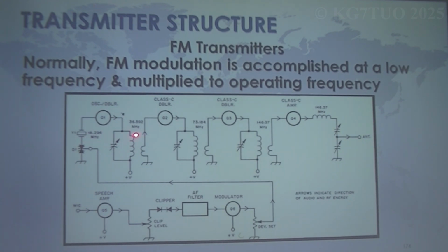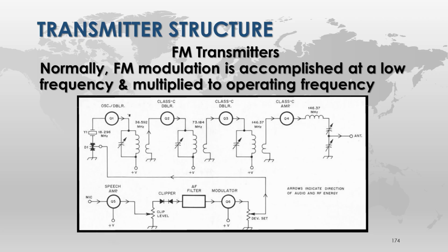That's how it works. Well, I see 4 turns and I see 2 turns. That should be a half. Well, it's not. Yes, the turns ratio is going to be weird, but we're not talking about that. We're talking about the resonant frequency of this one, which is resonant at 36 meg. This one is resonant at 72. This one is resonant at 144. That's because we have a capacitor and an inductor, which makes a tank circuit. That makes more sense. It's the resonant frequency of that tank.